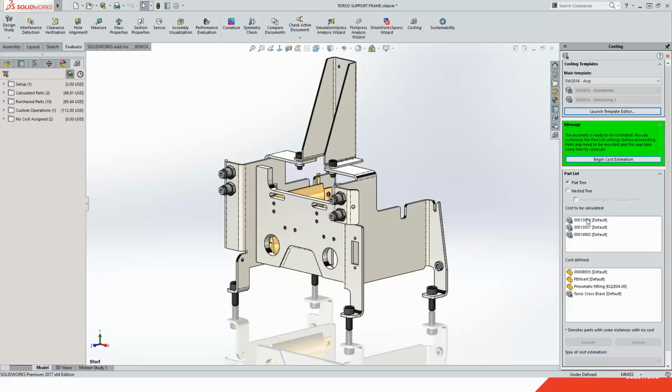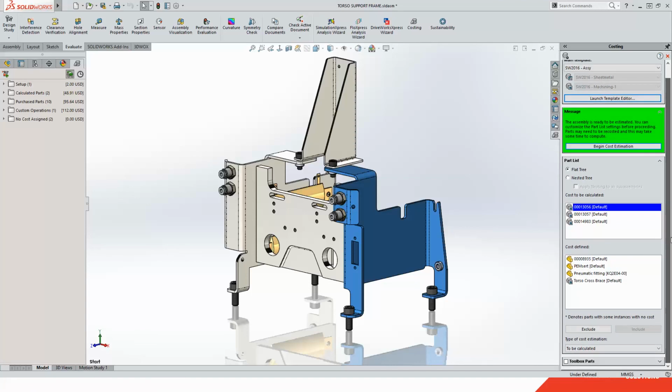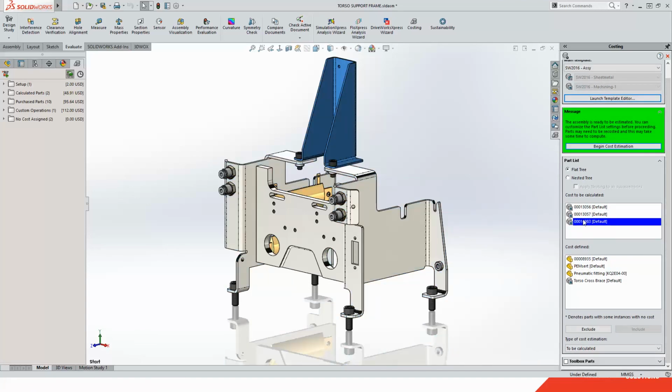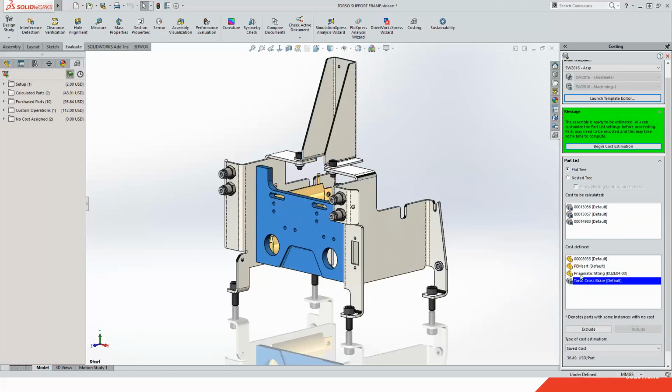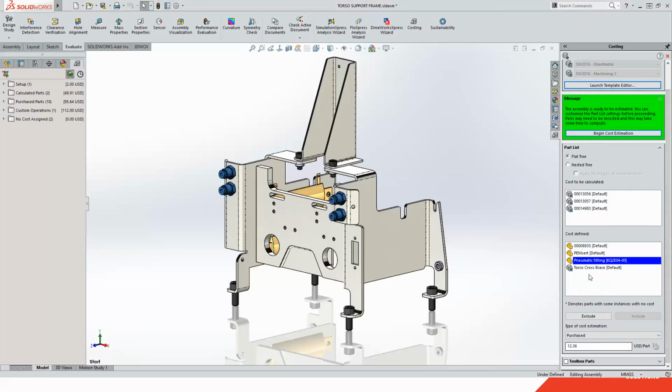It also shows us what parts have yet to be costed. So in this case, I'm midstream on that side part there, but that one's going to go ahead and be costed as a sheet metal part. This one over here on the side, also a sheet metal part, and then this one on the back, also a sheet metal part. But ones that we've already done are going to be things like that bracket up front. We have some purchased components. If you take a look down here, those purchased values are listed as hard-coded cost numbers within these components.